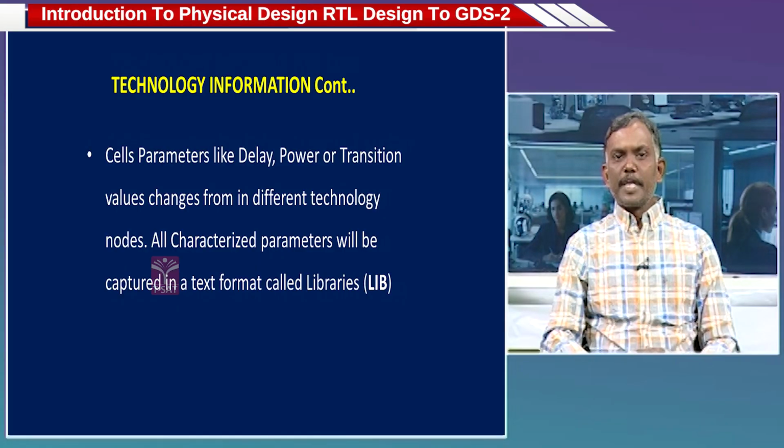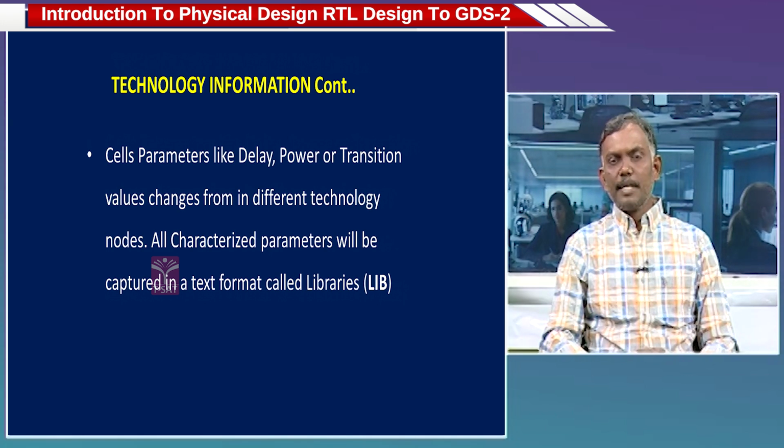These can be different values. Those can vary depending upon your implementation stage. For that, the fabrication people or library vendors will characterize those values for a given input transition, meaning with what rate the signal is coming and how much load it is going to drive at the design implementation stage. So the cell delay depends on that. Multiple combinations can happen, depending upon your design.